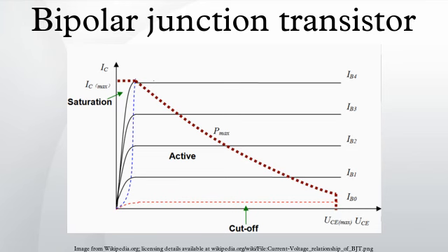This applied voltage causes the lower PN junction to turn on, allowing a flow of electrons from the emitter into the base. In active mode, the electric field existing between base and collector will cause the majority of these electrons to cross the upper PN junction into the collector to form the collector current IC. The remainder of the electrons recombine with holes, the majority carriers in the base, making a current through the base connection to form the base current, IB.